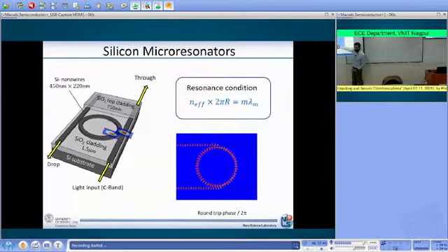And so your field is passing into the microring resonator, and then is traveling in this whispering gallery mode of the microring resonator. What happens is that this field can be sustained by the microring resonator only in the case where you have a constructive interference between the field that has entered here and the field that is reaching this point after one round trip, okay?